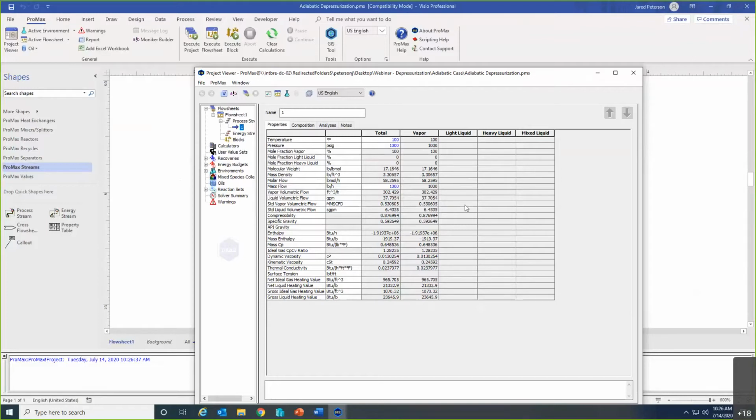For simplicity and time's sake, we are just going to start it right before relief conditions. We're going to pretend that my relief temperature is 100 degrees, my relief pressure is 1,000 pounds, and that the mass in my vessel at those conditions is 1,000 pounds. These are all assumptions I've made. Furthermore, I've assumed that my total vessel volume is 302 cubic feet.